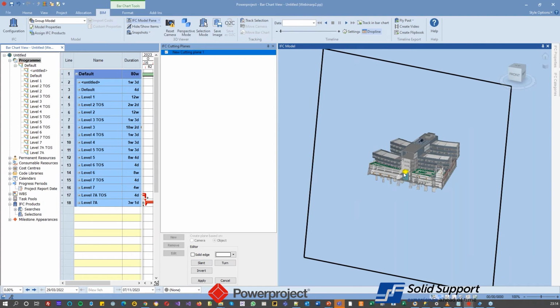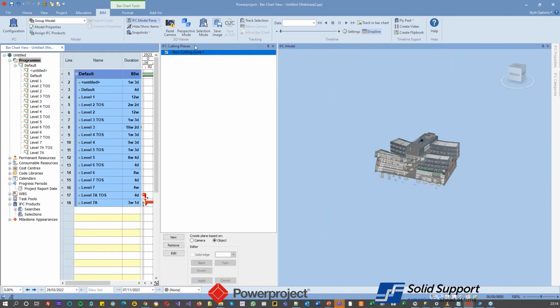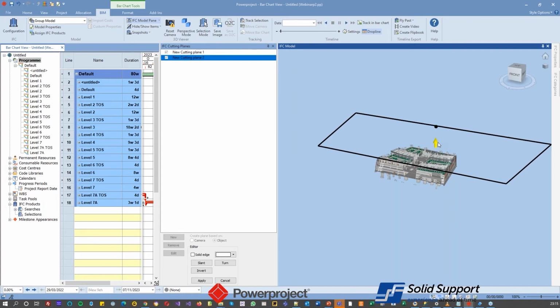And if I go in there and I click on an object inside there, you now get a little yellow arrow, which I can push through and cut through this model. And you can see I can do that. Now, if I come out, you can see that's the box that it's actually got. It's moving around. If I want, I can slant that forward or backwards in there. And if I did that, and I move, it now moves through at an angle.